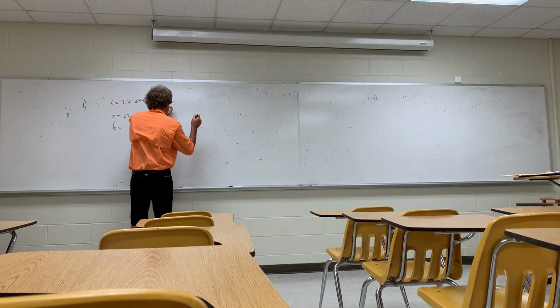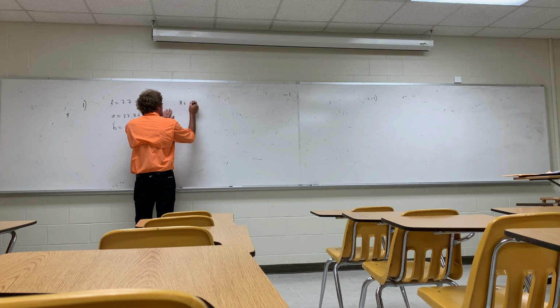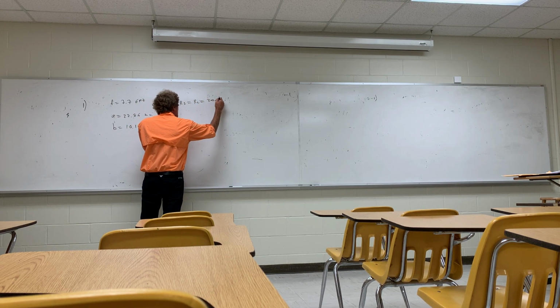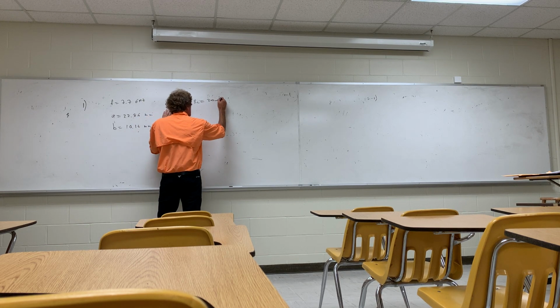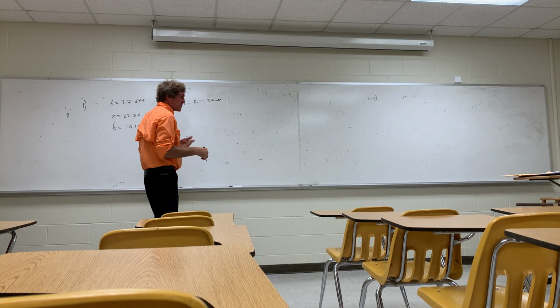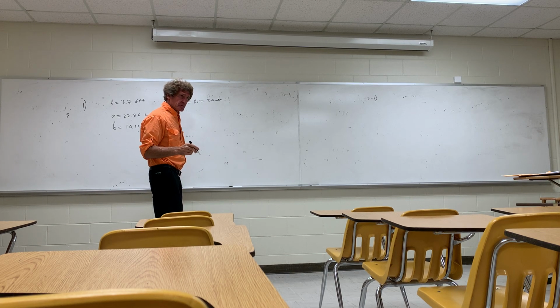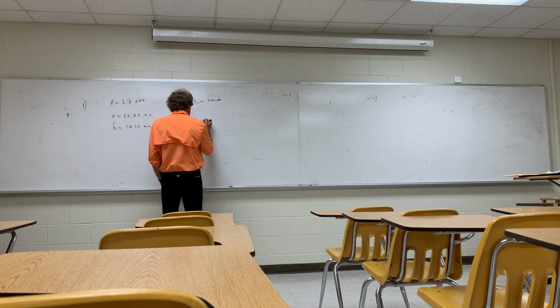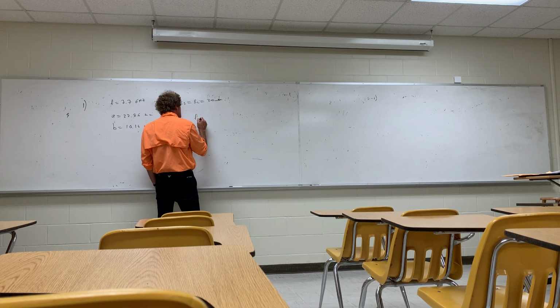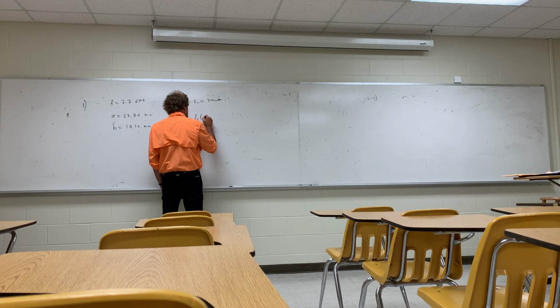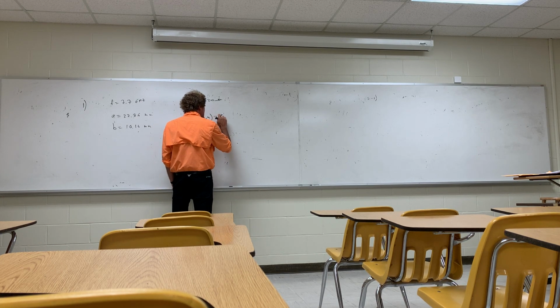Give you a source resistance equal to a load resistance of 200 ohms. And it wants to know, first, I guess we'll do the modes first, which makes logical sense. So first thing we have to calculate is the actual cutoff frequency for each mode, M comma N, and get the three lowest modes.